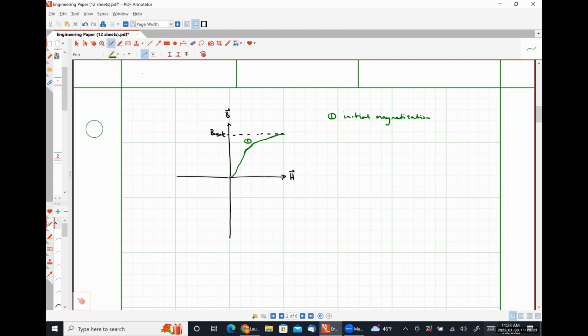As we remove our magnetic field intensity vector by just effectively turning down the current that we're using to generate the field, we'll see this region of our curve here too. So when our field gets back to zero, there is some B field in a net direction that's left over, right?